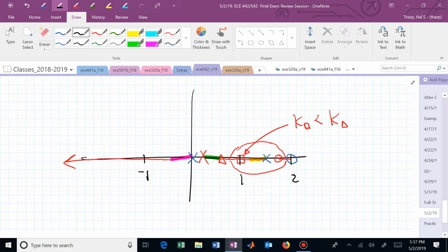So you would now be saying, oh, he needs a stabilizing controller. Let me just check triangle, that point. Okay, there's my answer, but I need to verify that. Now you would check the gain at box and the gain at diamond. And then you would say, okay, this is going to work. Or you would say, whoops, it didn't work. I now need to back off. And hopefully K box is less than K diamond. If it is, then you can say, okay, maybe I cranked up the gain a little too much to get me to triangle, because that now sent diamond beyond -1. Do you see how to maybe think through this process?